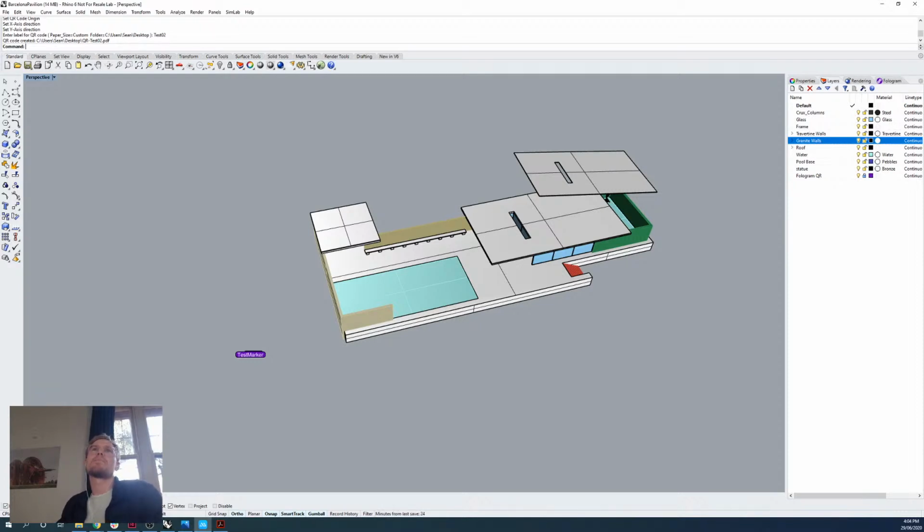Cool, so if you haven't used it or heard of it before, Grasshopper is an algorithmic plugin for Rhino that gives us parametric control over a series of relationships that we're able to create through node-based components. That's kind of jargony. Essentially what it means is that we can create infinite design options through a series of relationships that we design and control inside of Grasshopper. And we can extend this control directly into our Fologram session.